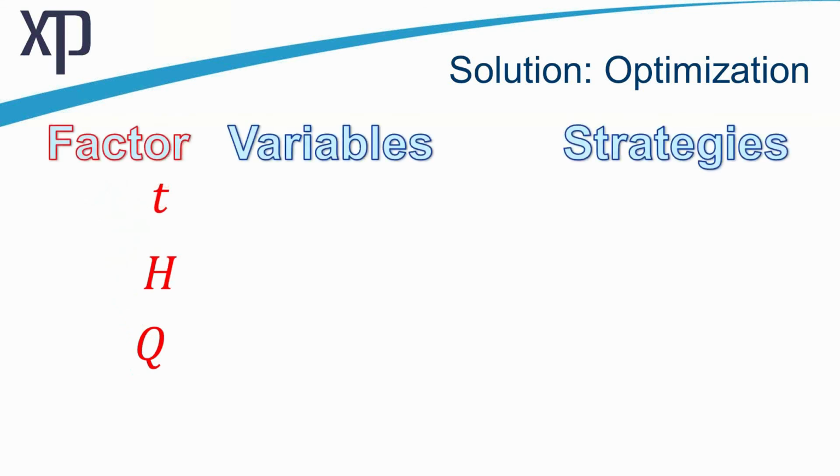So we'll break that up into factors. And so those factors have variables that affect them as well as strategies that a model can help you address. So we'll start with time, and some of these are interrelated. So I'm simplifying here to say that the wet well size or the suction size storage size is a variable for time. Obviously flow and other things are, but if we start there, we know the wet well size, so there are strategies in the storage design of that, both the depth as well as just the sheer magnitude of the wet well and its placement.